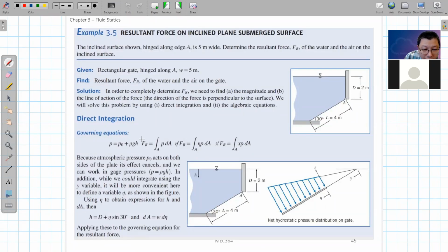We try to calculate this pressure force directly from this integral itself, and simply put P0 plus rho g h into this P, and over dA we can calculate it. And H, what's it at any location point here? This length H will be equal to this D plus.